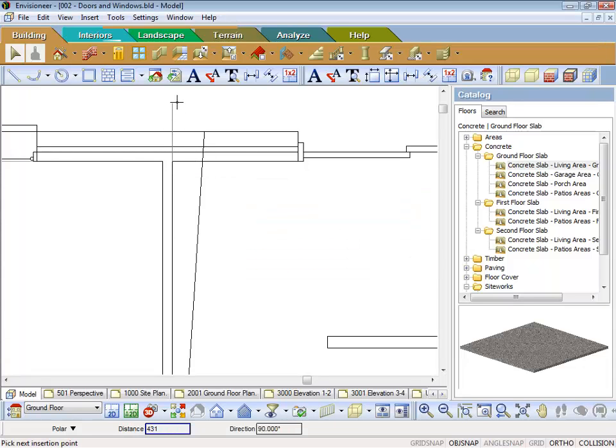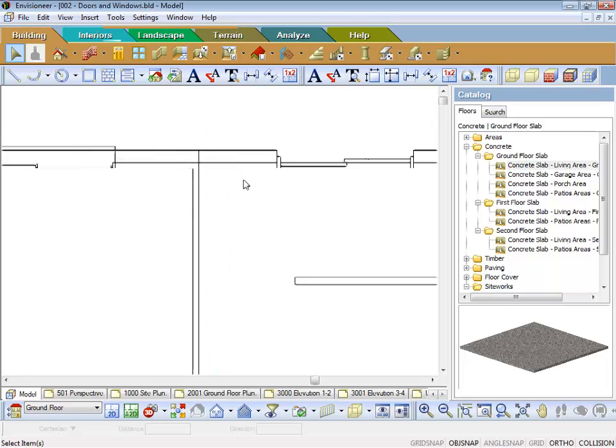And then if I draw it up, see how it's just following me up? So if I just drag my mouse up in the direction I want the line to go, let my mouse go and watch the commander down the bottom where it's got distance, I'm going to type in there 220 and then hit enter. Right click and finish. That gives me a little line in there with this endpoint that I can now grab this surface. So I'm touching the surface, move my mouse over that blue point, hold it down, and then move it back over to that line and it'll snap to it.